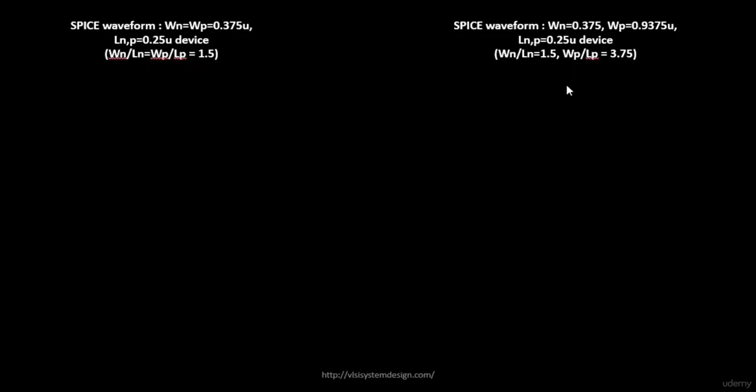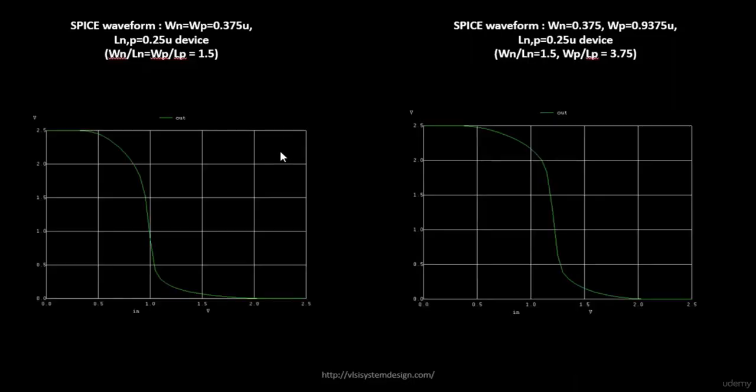We'll set plot, and we'll see what is the new plot that is available. These were the past plots that were available, and we plotted DC1 for your previous case where your PMOS and NMOS widths were the same. In this case the current plot is DC2, and this is the case where your PMOS and NMOS transistor widths vary by 2.5 times. So this is DC2, so let's set that plot. Okay, display, let's look into what is available with us. We again have the in node and the out node available. So let's plot them: plot out versus in.